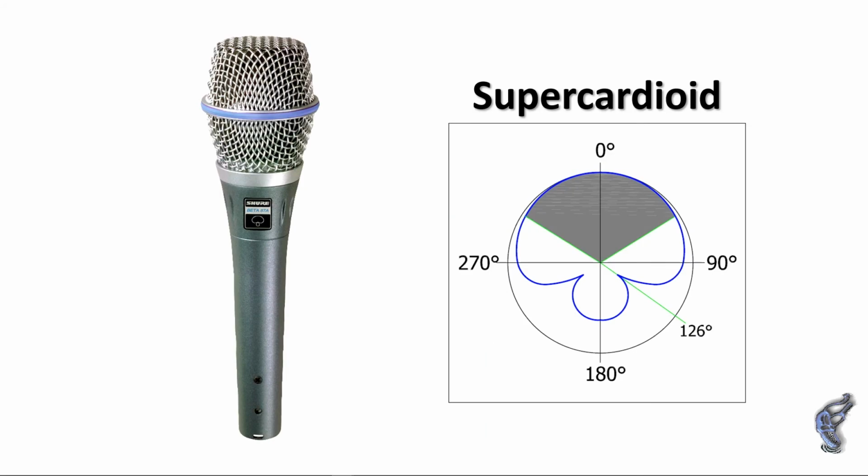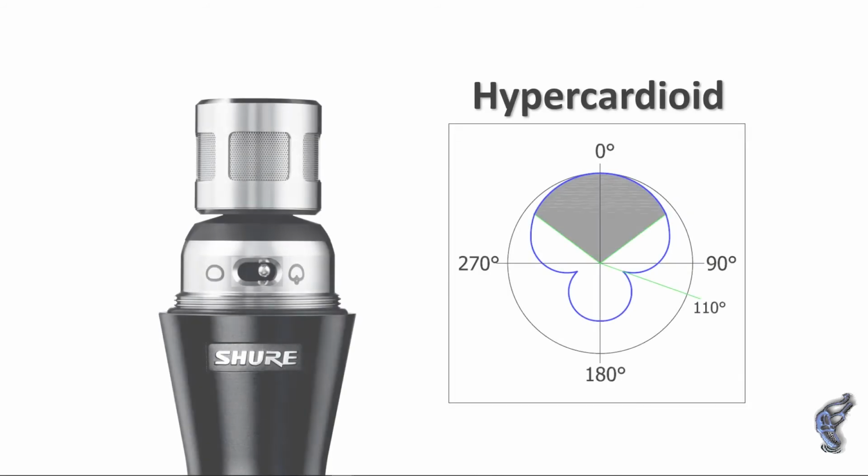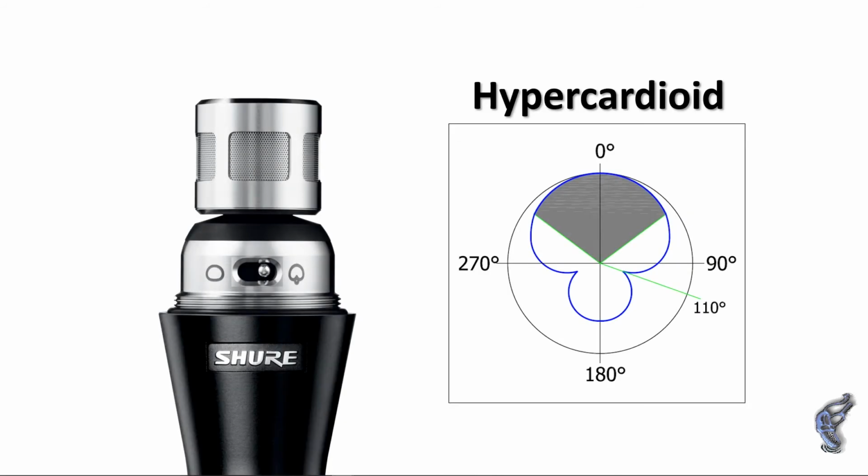The supercardioid pickup pattern has an even tighter acceptance angle, 115 degrees. When used for a vocalist, it is intended to be used as a handheld mic or on a stand very close to the vocalist. It could be used by two vocalists, but typically is just one person per mic. The reason to move from a cardioid mic to a supercardioid mic is further improvement in gain before feedback. The same can be said of the hypercardioid mic. Its tighter acceptance angle yields even better gain before feedback.